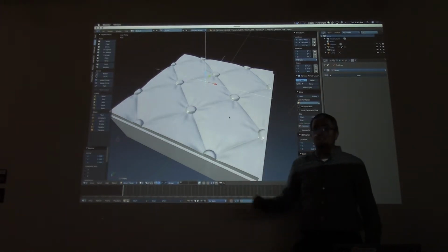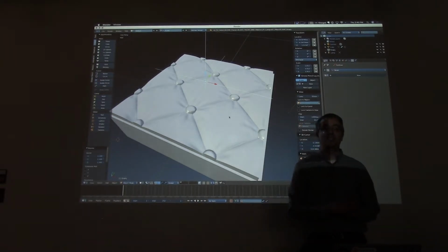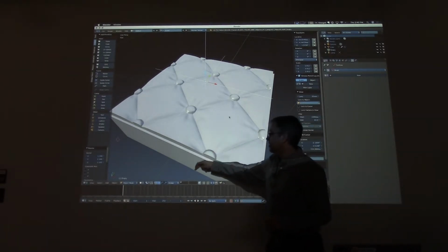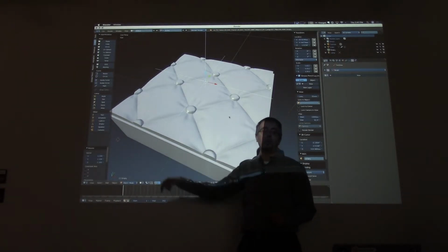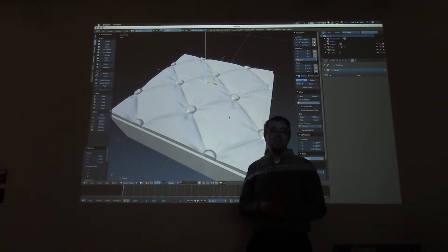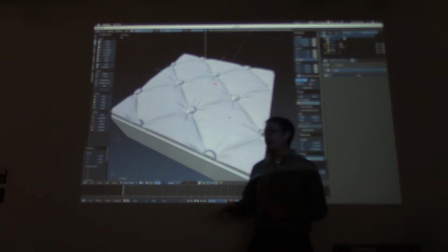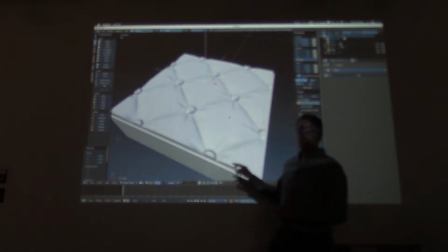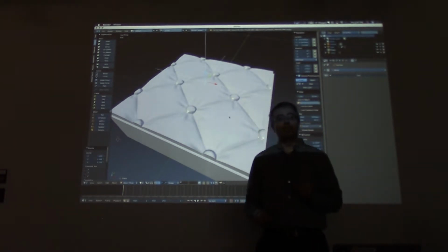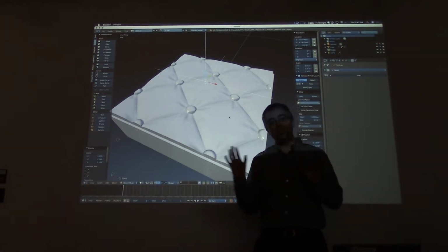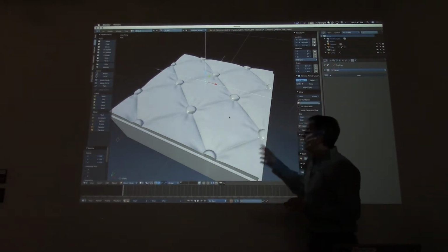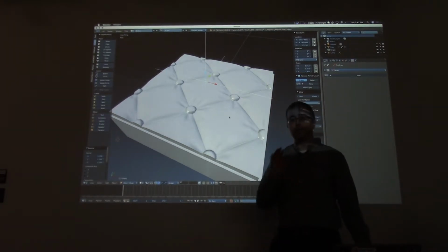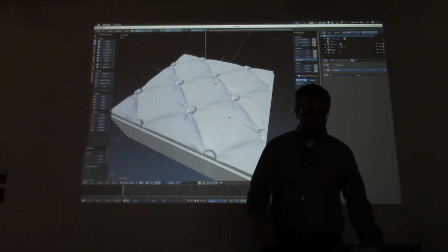This is one of those things that I might learn differently on Friday, but I suspect we're going to need a little bit of an edge on the edge, because what happens otherwise is your drill bit will actually try and go around and carve the side of your wood block if you give it this STL file. So to be careful of that, I suspect that we're all going to need to leave like a little 1/8 inch of an edge, just as a side note. So in general, think about doing something like this, but it's not critical at this moment. We can fix it later if we need to.